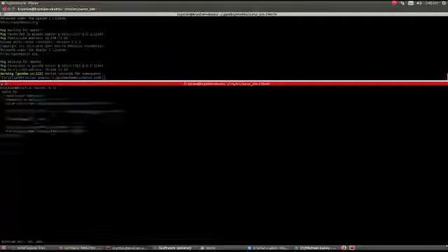We're looking at package.xml here, and here we'll just briefly put in the name for the package itself, the version, just a short description, email, and stuff like that. The dependencies. We don't really have much code that needs build dependencies, so this actually doesn't really need to be there. I'm just going to leave it anyway. A run depend. So we use robot localization as the Kalman filter node later that I'll talk about, but this is pretty much the only dependency during runtime that we will need.